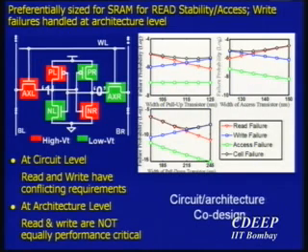The other thing that we looked at, and I thought this was interesting, and I just briefly wanted to mention, is the fact that different kinds of decoupling are possible. In this case, what we decided to do is take the 6T cell and size it. How am I going to size it? I'm going to make sure that there are no read failures. So what does it mean? I'm going to have write failures. If I do have write failures, from the architecture point of view, my friends in the architecture community tell me that read is more important than write. And there are different write schemes and so on. So what I can now do is give an extra cycle for write. If I stretch my word line a little bit longer, then my write failures go away.